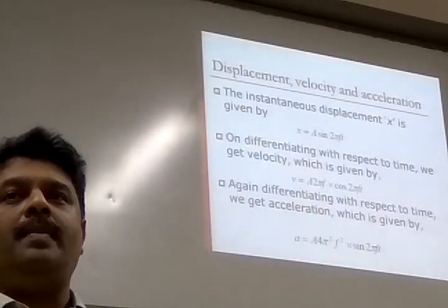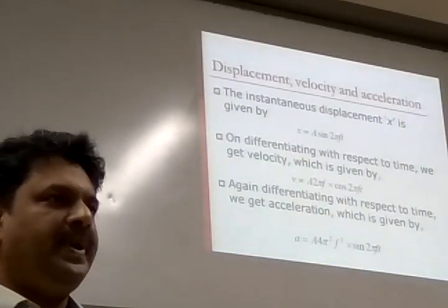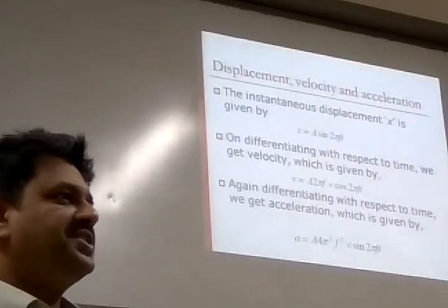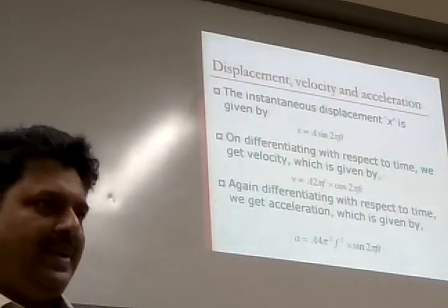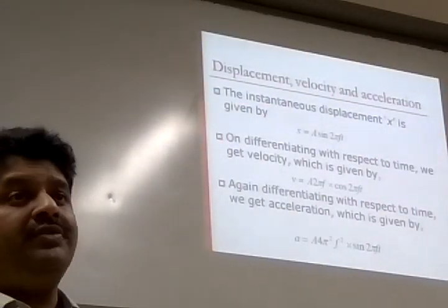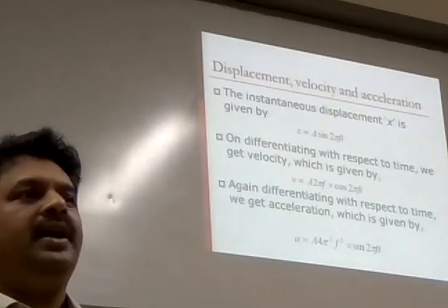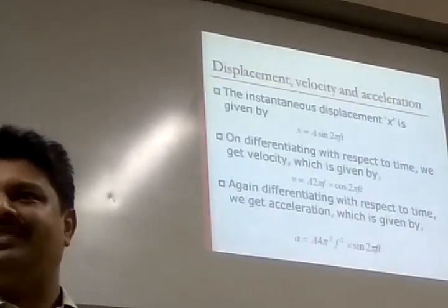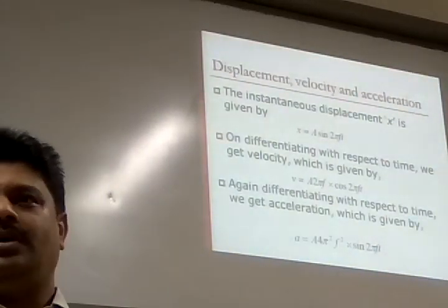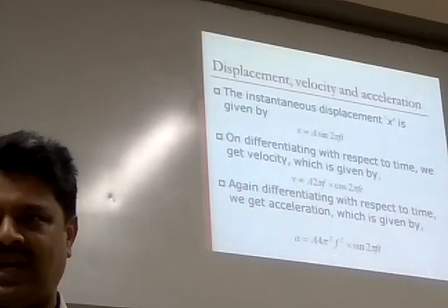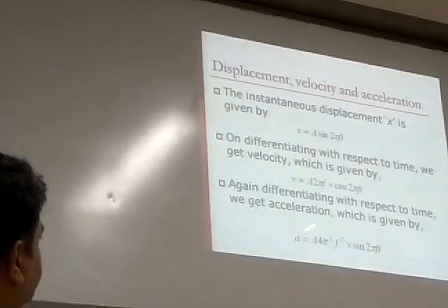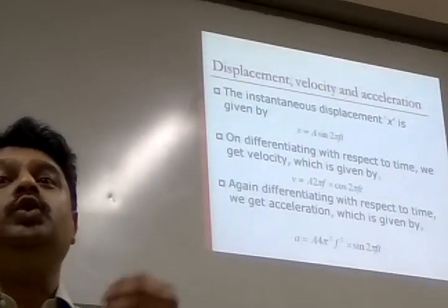Why does acceleration become so common? Because normally the rated speed of a motor, the rated speed of a fan, for most of the motors that are available commercially, is at least 1440 rpm. You might have heard around 1400 rpm. 1400 times it will rotate in 1 minute. That's actually a high frequency signal. That will produce a high frequency signal. For such machineries operating at that much speed, the vibrations we get are all high frequency signals, so we should worry about the acceleration signal for those machineries.